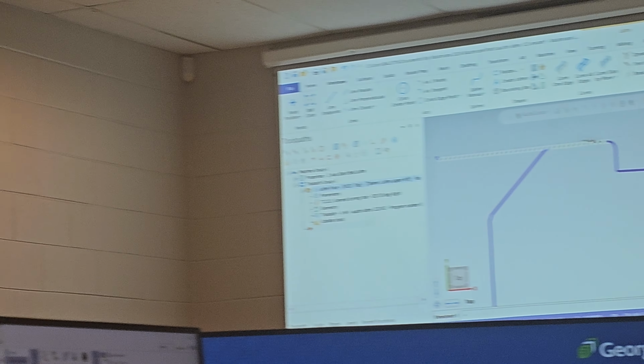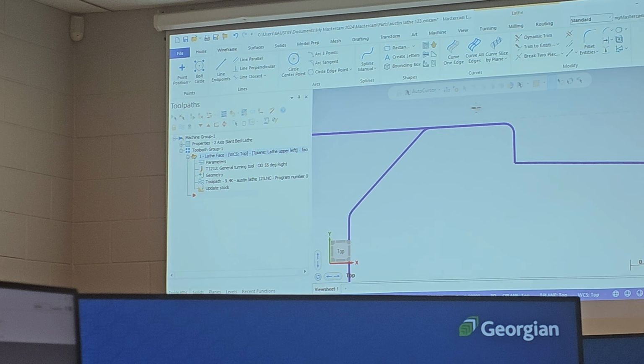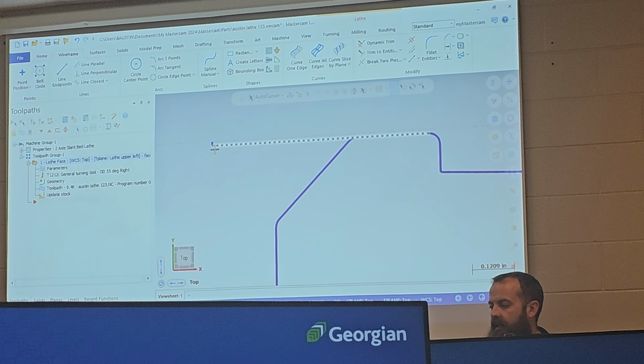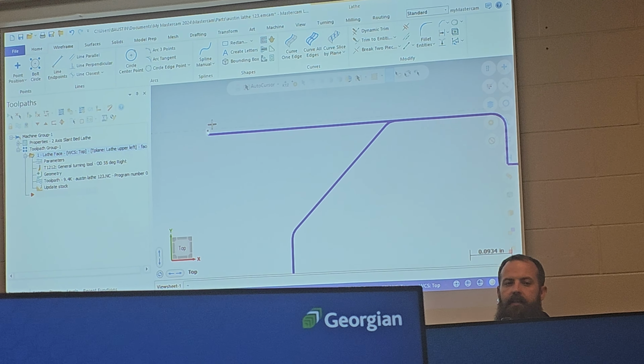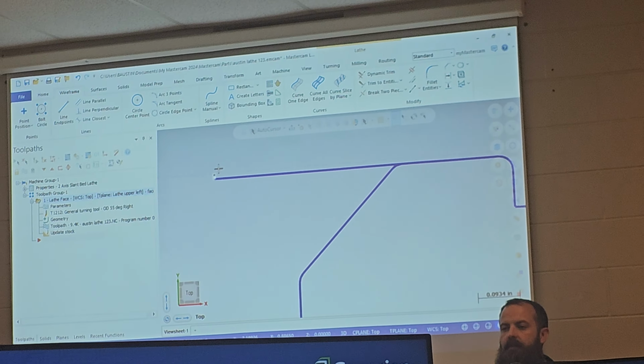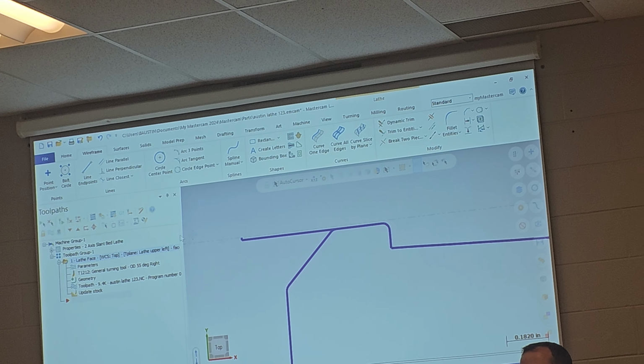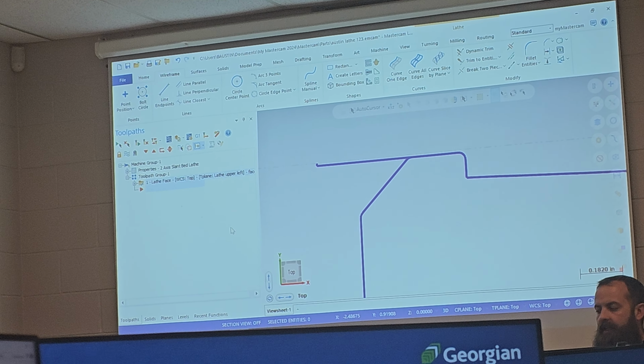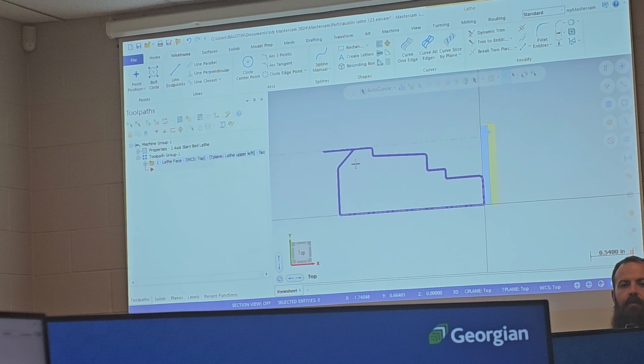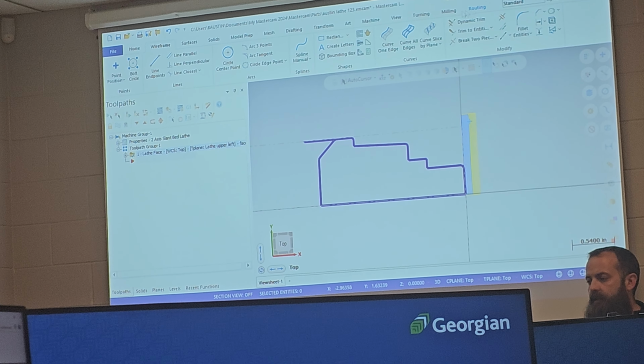Okay, so I have a line that is the same diameter as the part. It goes a little bit past where it is, and then provides a shoulder. And the reason it's doing that is it's roughing the bar off for the parting tool to come in. Okay? After my line geometry looks like that, I have a very simple tool path to control the majority